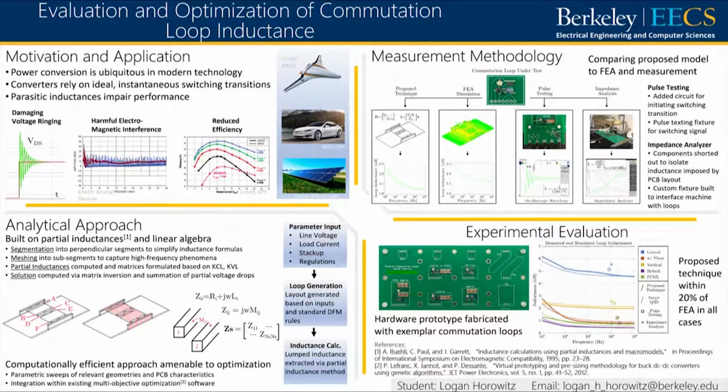In order to validate this approach, I have compared the results of the proposed program to other tools for estimating inductance which are typically used. The first is a highly detailed finite element solver software, which is much more complex and also requires the use of a proprietary software. The next is a time domain measurement where we attempt to switch the converter and look at the voltage ringing that occurs in the circuit. The final test is done by using a piece of equipment called an Impedance Analyzer to directly measure the inductance.